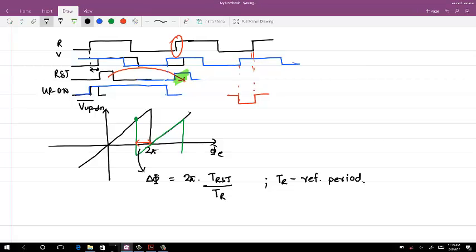Okay. If you remember when we started initially, the XOR PD or SR flip-flop phase detector, we told that even for the positive phase error, they are having positive and negative regions also, which is one reason their frequency acquisition range was very limited. Right, now with the PFD, we are landing in the same problem because of the way we are implementing it.